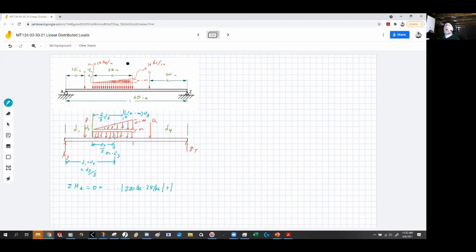And then the triangle part, the linear distributed load, 2/3 D3. So D3 is 22. So that's going to be 7 1/3 times this distance here is 16. Sorry, this difference here is 6. Okay, so it's not too bad. So I've got 22. Watch why I use the units, okay? So I'm going to calculate this out here. This phantom force here is going to be